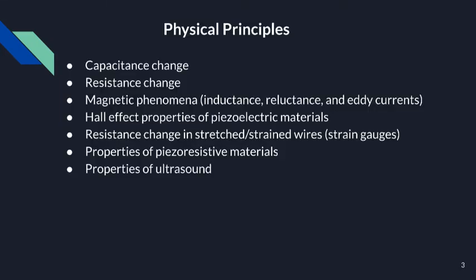The physical principles that we shall examine are capacitance change, resistance change, magnetic phenomena, including inductance, reluctance, and eddy currents, the Hall effect, properties of piezoelectric materials, resistive change in stretched or strained wires or strain gauges, properties of piezoresistive materials, and ultrasonic properties of ultrasound.